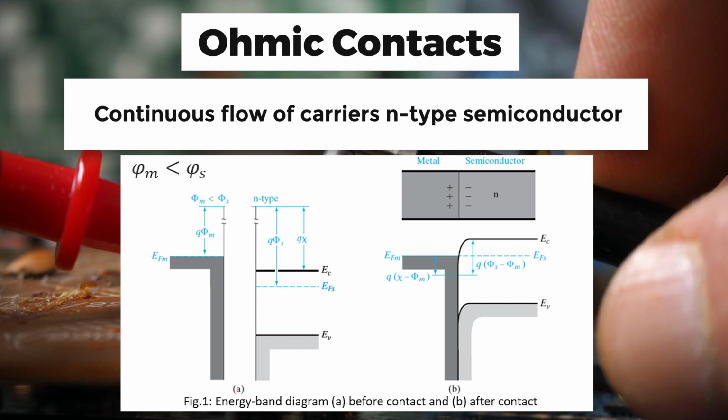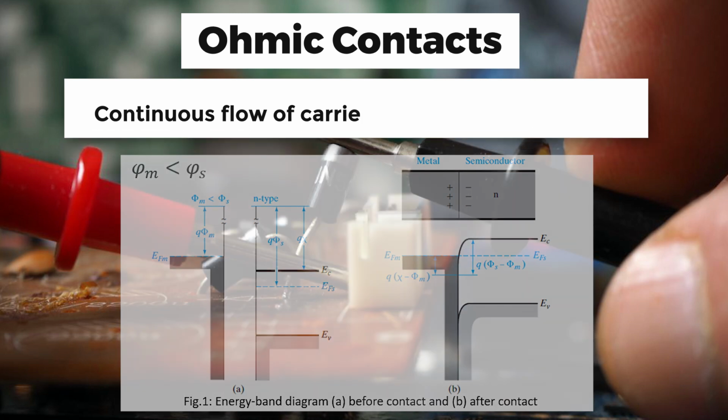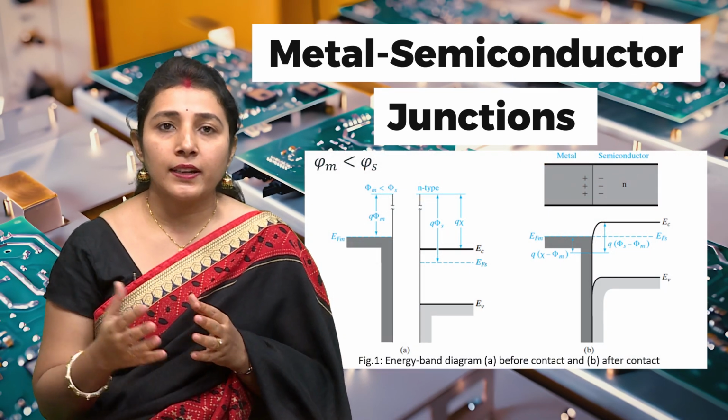Hence, we can say ideal metal semiconductor contacts are ohmic when the charge induced in the semiconductor is aligned with the Fermi level provided by the majority carriers. Here the charge provided is because of the majority carriers of the n-type material. In the n-type material, the majority carriers are electrons. So, electrons came to align the Fermi energy level. Such types of contacts are ohmic contacts. So let's take another example.